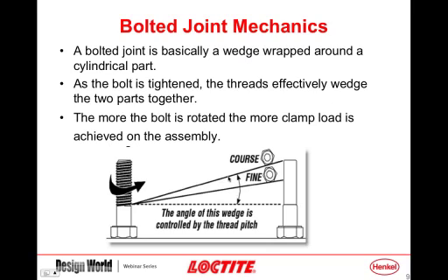And the functioning of the fastener is very simple, very fundamental, and that is you are taking and driving the threads of the nut along this ramp. And as you drive it along the ramp, you are reaching the point where the fastener is secure, and then as you further move the nut along the ramp, you actually start to stretch the bolt. And when you start stretching the bolt, that is what creates the clamp load. That's what you're paying for when you have the fastener. And that's what provides the functional benefit of the fastener.